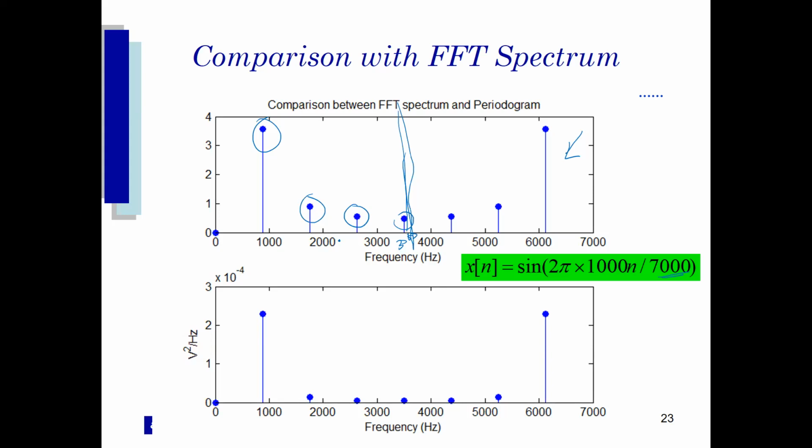If you were to run the periodogram on it, which looks at the power spectral density of this, the power in the signal, we know it's a 1 kilohertz signal. So we know that the most power is going to be associated with this, and less so with these artifacts. These are a result of leakage.